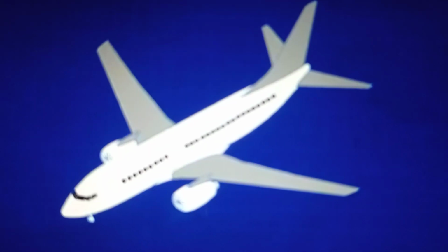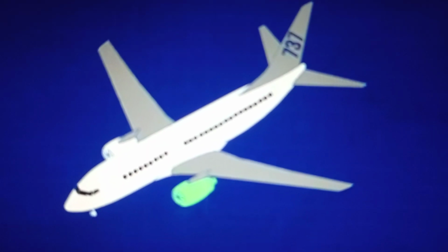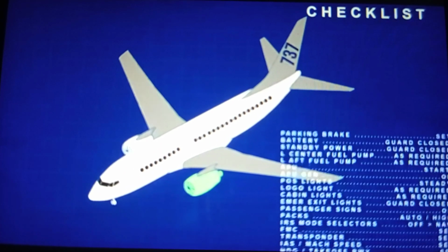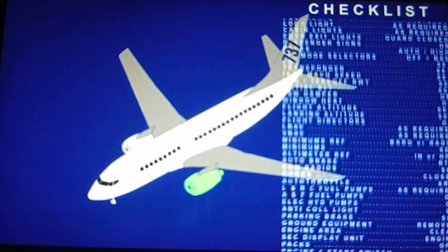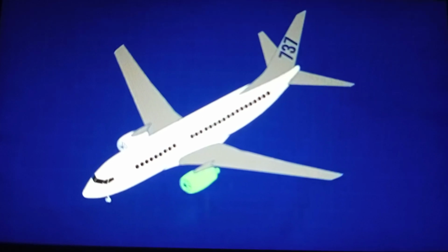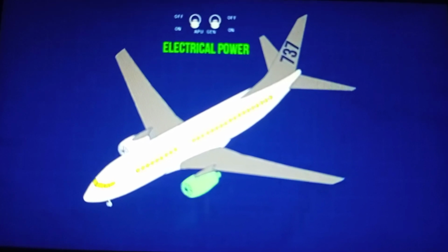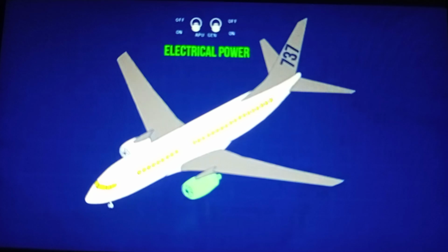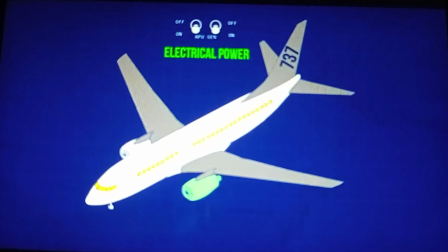Start an engine on the Boeing 737. A number of tasks in a checklist have to be followed. The ones directly concerning engine operation are: aircraft's electrical power has to be established for operation of two computers that play a vital role in a successful engine start: electronic engine control, located on the right side of the engines, and display electronics unit, located in aircraft's electronic compartment.